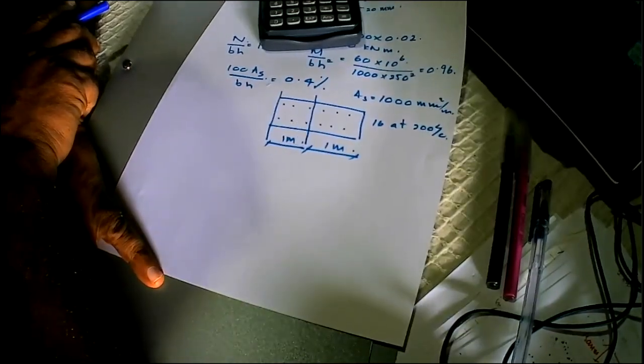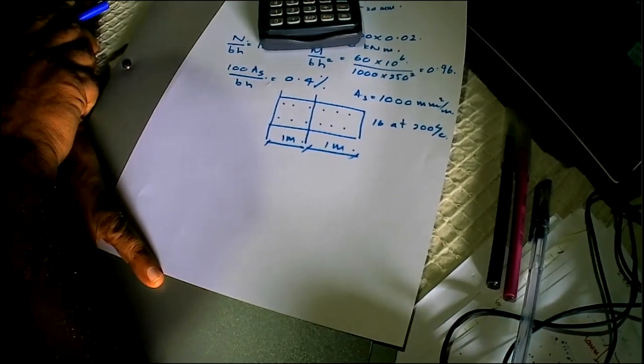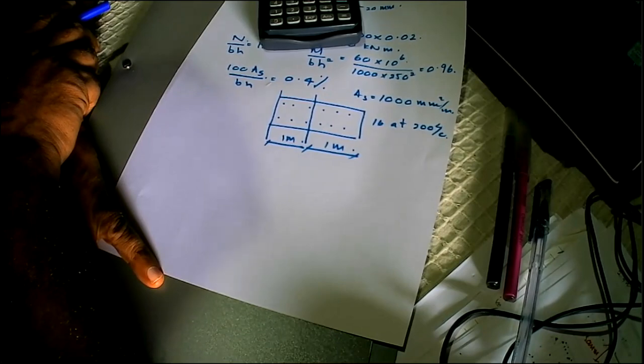So we don't like a shear wall that is not supporting any slabs, because if the shear wall is supporting slabs, then at each floor level the slabs can transfer a certain amount of load onto the shear wall, and that will stabilize the shear wall. Is that clear?